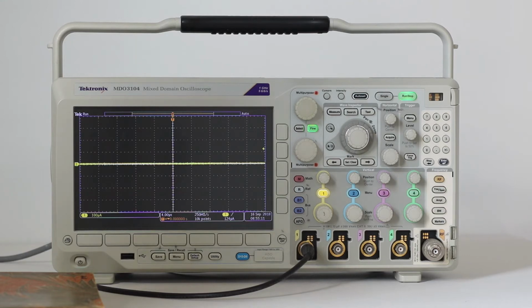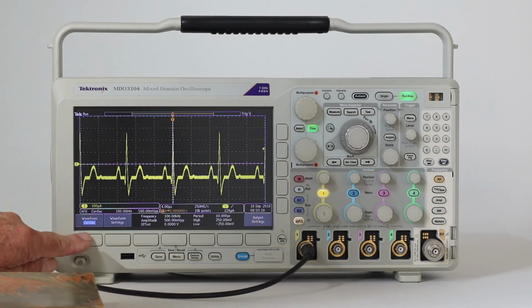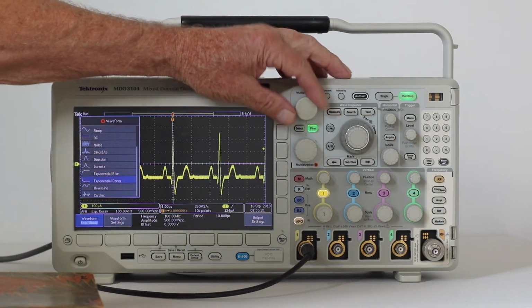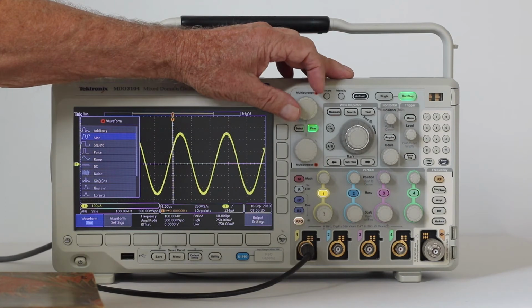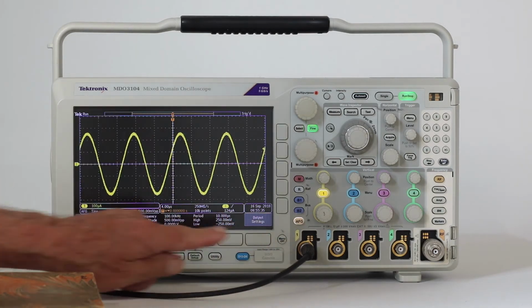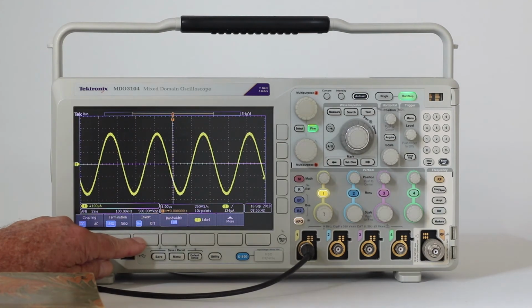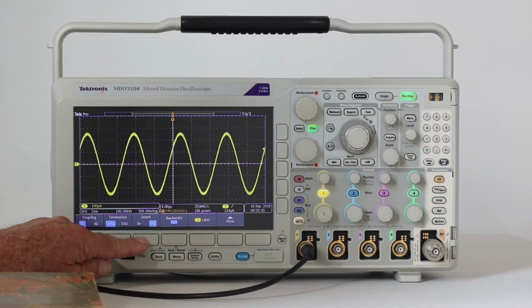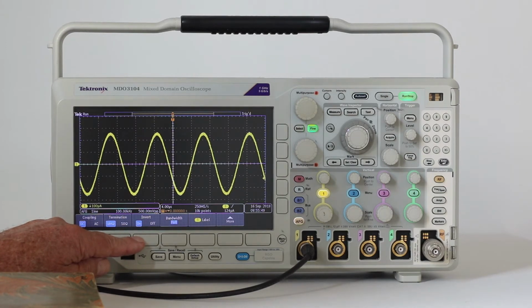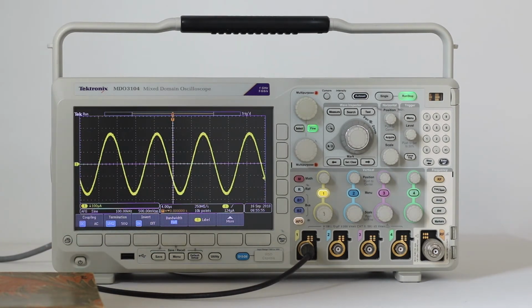This control reverses the polarity of the waveform. Using the internal AFG output fed into channel 1, this is what it looks like. If normal and inverted zero offset sine waves are added using the math mode, the result would be a flat zero amplitude trace.